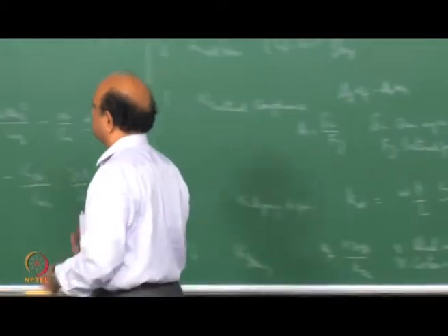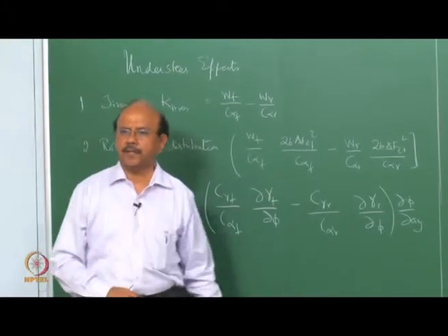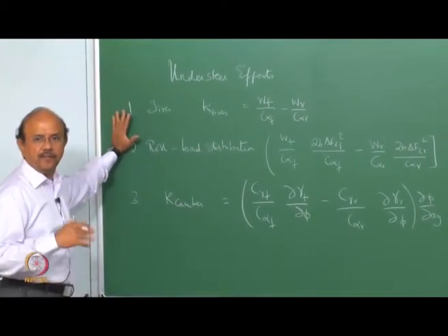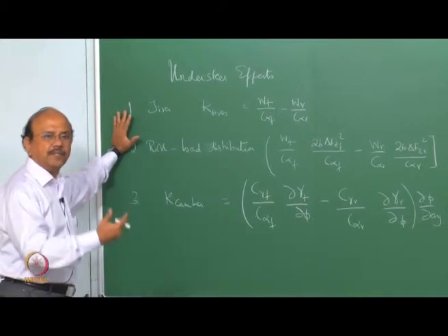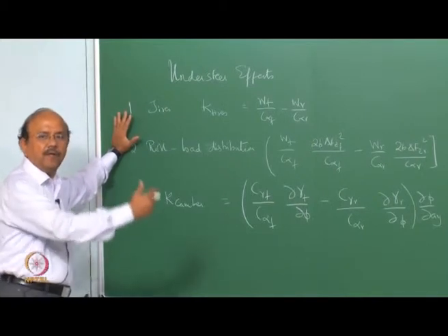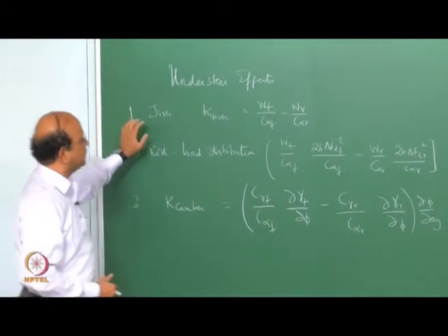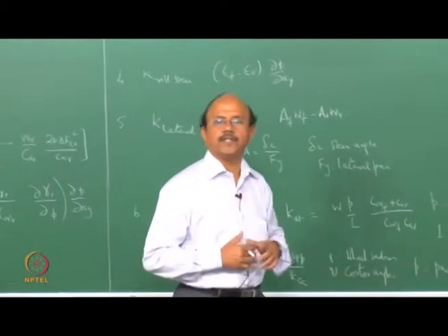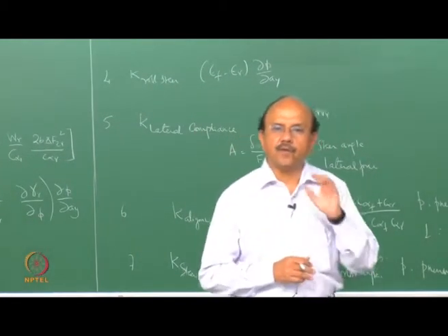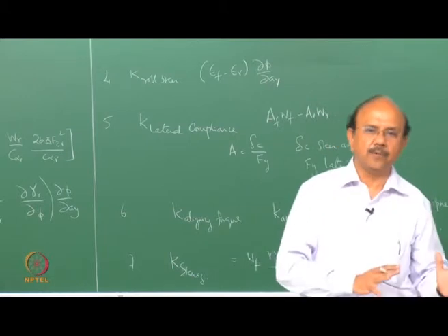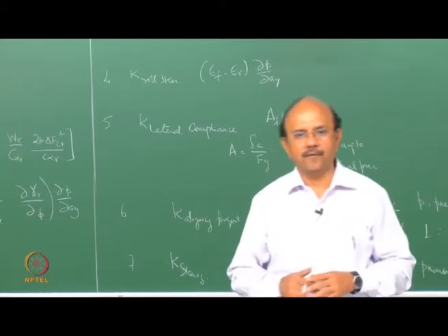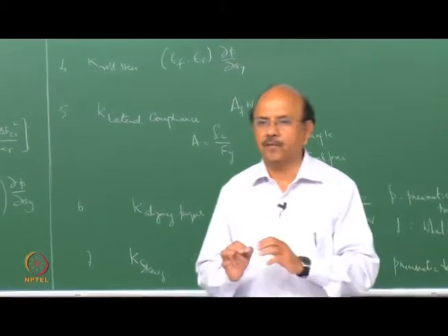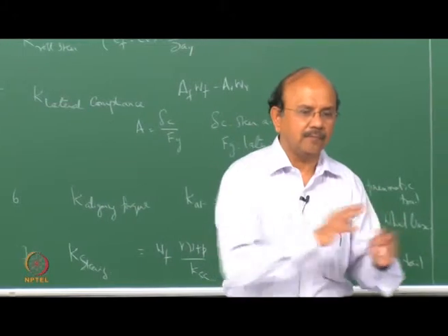Essentially, what we did was initially to look at understeer gradient from the point of view of the tires. That's the first thing. In fact, the whole language of understeer gradient was talked in terms of alpha f, alpha r, and so on and so forth. When we expanded the concept of understeer gradient, we were concentrating on the steering input and the corresponding behavior of the tire. In other words, whether I have to give more steering input or less steering input. This is what it came to.